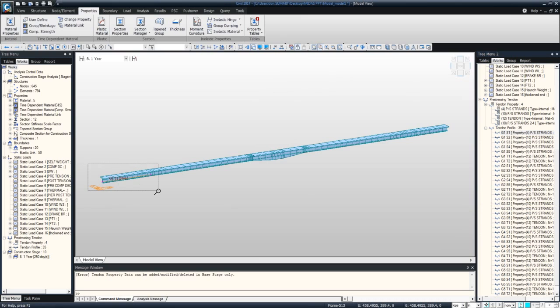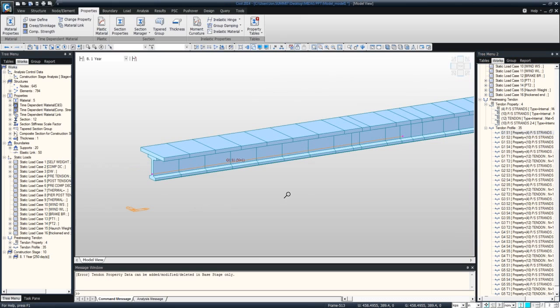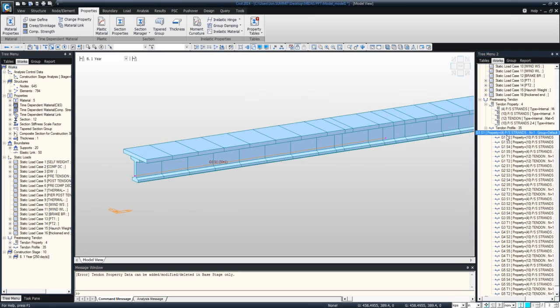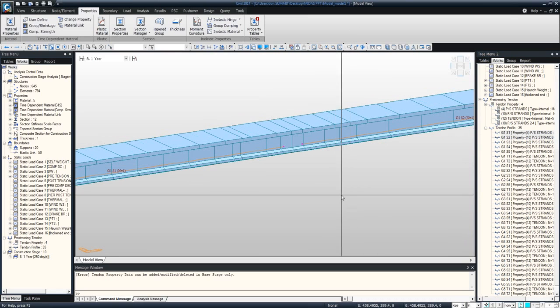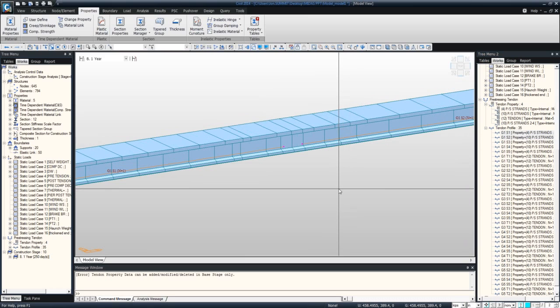Okay, so here we have the post-tensioning strand in the first girder segment. Turn on 1 and 2 so we can see how that does not go through the splice. And there we go. We have bottom pre-stressing in the pre-stressing bed that does not transfer through the splice. We do that for all 5 girder segments.